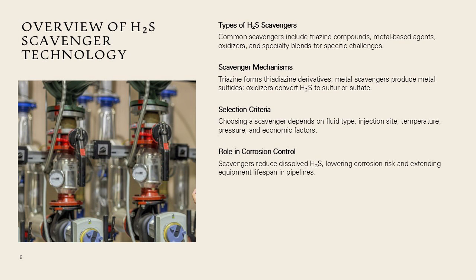Metal-based scavengers such as iron oxide or zinc oxide react with H₂S to produce metal sulfides, though application is typically limited to solid phase or filtration systems. Oxidizing scavengers convert H₂S into sulfur or sulfate through chemical oxidation processes but may require careful handling due to reactivity